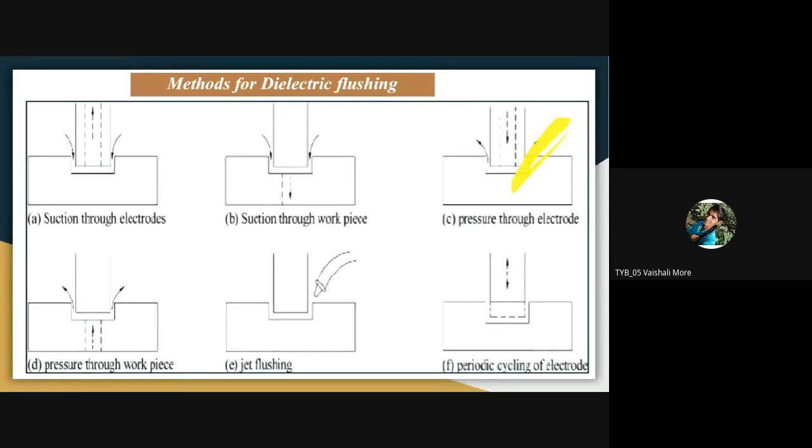In the first case, the dielectric fluid is coming like this, you can see the arrow, and you can suck through that hollow tube inside the tool. Then in the second, you can suck your dielectric fluid through the workpiece.